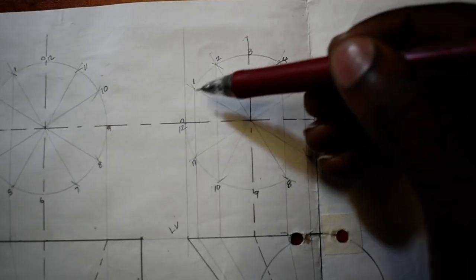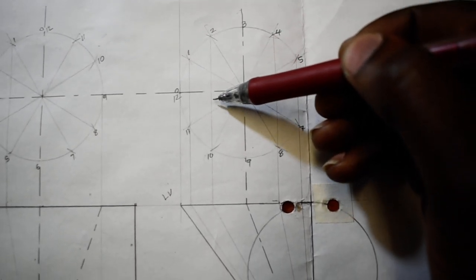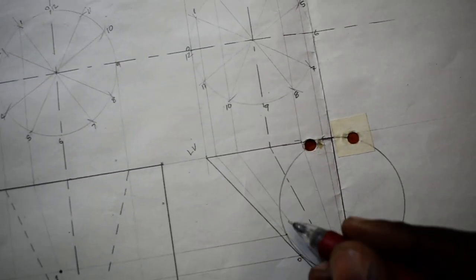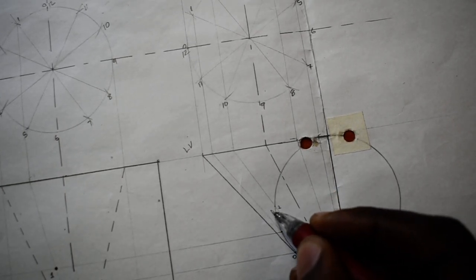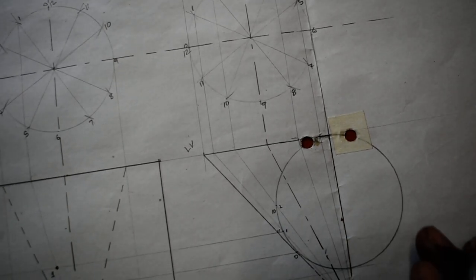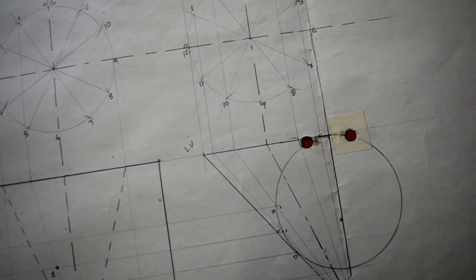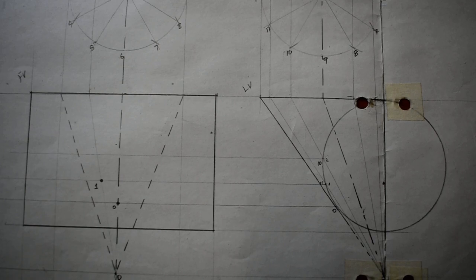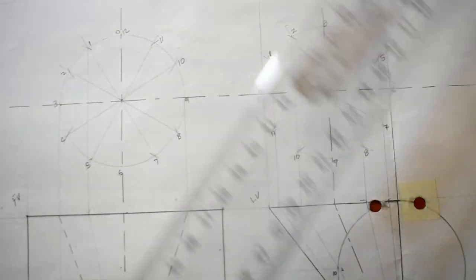So let's go to point 2. We've gotten 0 and 1 and 2. So this is point 2, there it goes. Once it touches there, it goes to your apex point, isn't it? Once it touches the main pipe, there it is. So I have a 2 here in line with 10, and this is 1 in line with 11. So take the point 2 in line with 10 towards my front view. Now go back to the auxiliary of your front view, construct the point 2 in line with 4. Take it vertical.